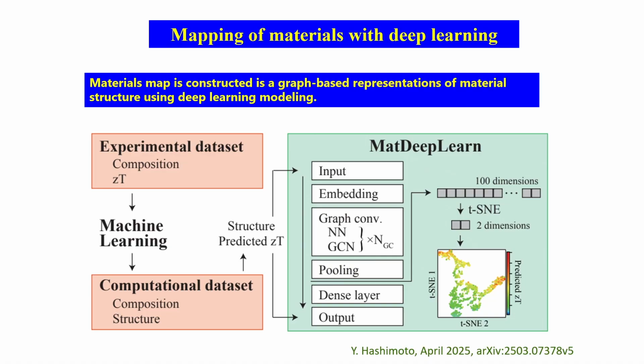One of the parameters which provides you the comparison of how the material behaves in terms of conversion of thermal to electric energy is ZT, and ZT can be experimentally measured obviously, and it depends on particular material compositions, processing conditions and many other aspects.